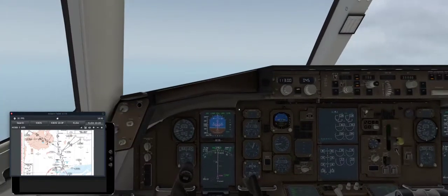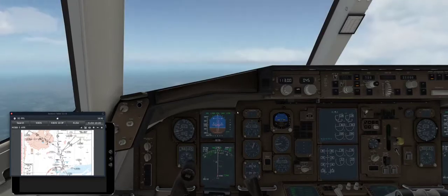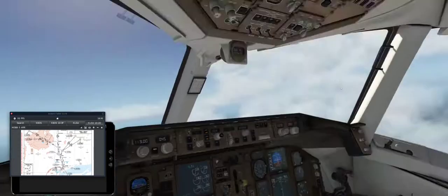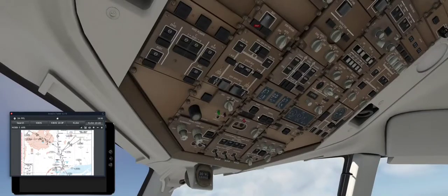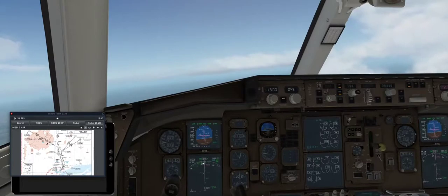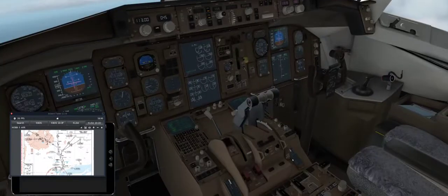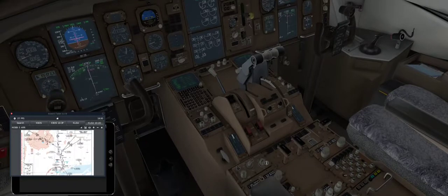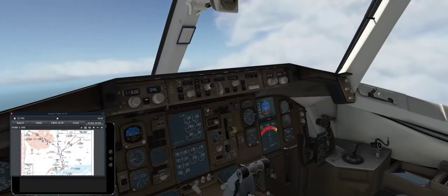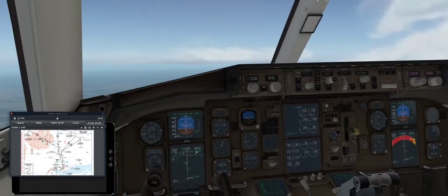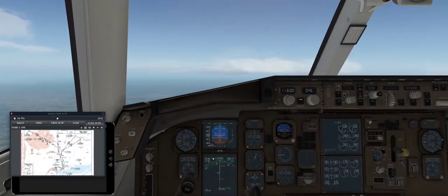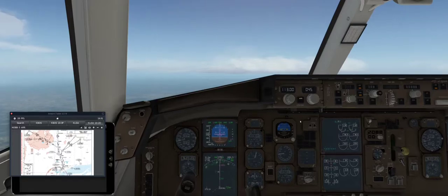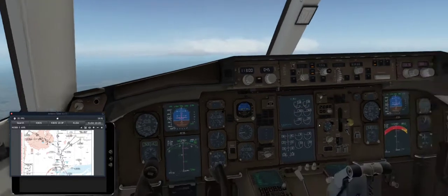We don't have any moisture in the clouds. I'm not going to have to worry about anti-ice, engine and wing. Here they are. If I had any red activity, weather activity, I would certainly want to. Yeah, we get red stuff on here, but I don't worry about that too much. It's when it's red on this more advanced system that you know there's moisture, and you'd be taking a big risk by not using your engine anti-ice and your wing anti-ice. Why wouldn't you want to do that? Well, it does take some power, as well as cause wear and tear on those systems.